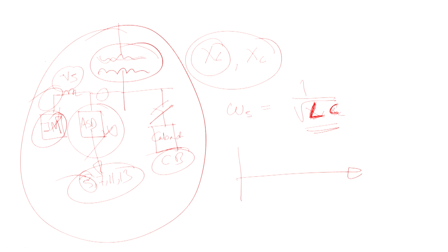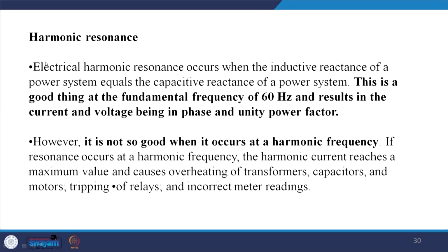So, this is a very big disadvantage of this capacitor. Let us go back to our discussions. This is a good thing at the fundamental frequency, 50 or 60 hertz, and it results in the current and the voltage being in phase with the utility power factor. That is a good part of it, but the worst part of it is that it may cause harmonic resonance. However, it is not good when it occurs at harmonic frequency.